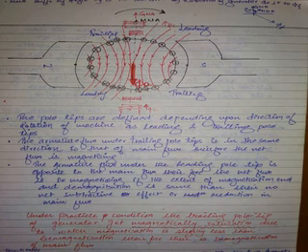For example, if the amount of increase is equal to the amount of decrease, what is the net demagnetization? Zero. If the amount of decrease is more than the amount of increase, will there be demagnetization or not? Yes. Definitely it will be, right? Means the increase in the flux is only 0.9 Webers, the decrease in the flux is 1 Weber. Is the point clear? If the increase in the flux is also 1 Weber, there is no demagnetization, just cross-magnetized, only that.